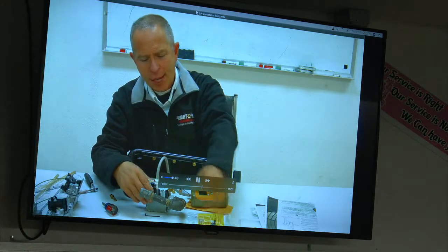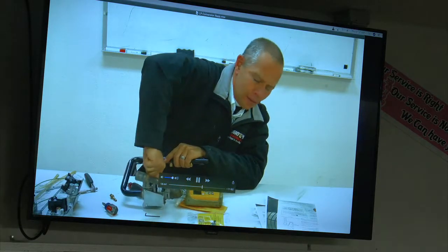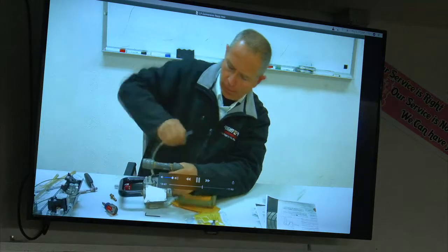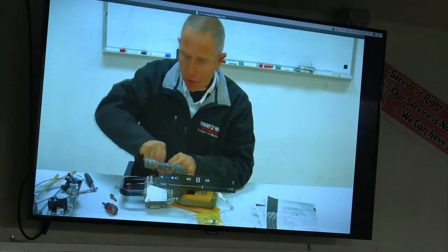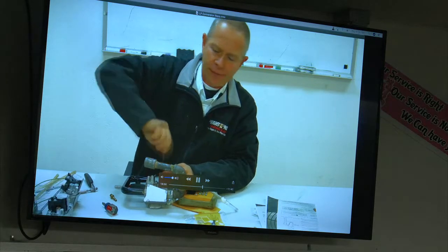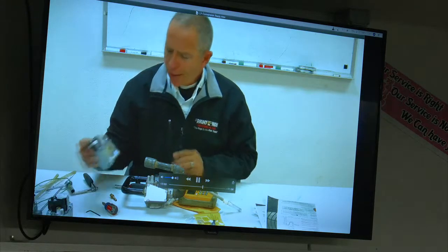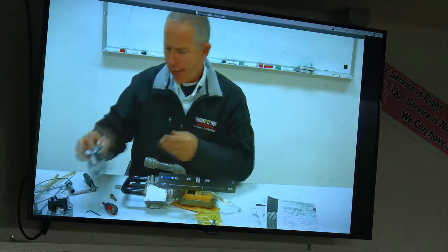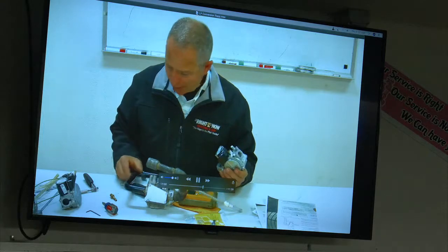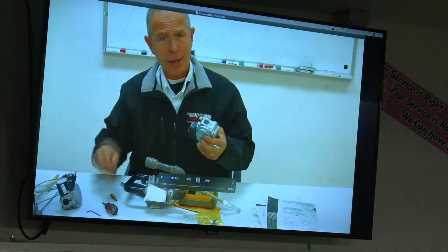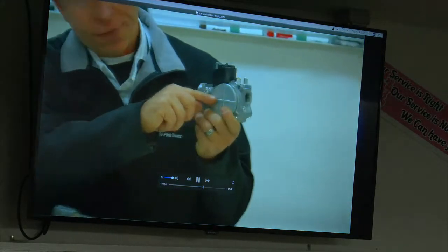So now that you have all that done, again, you're going to turn the gas off and disconnect your meter. And you're going to take that set screw and put it in and make sure it's snug. You're going to use a little bit of leak check and make sure you have no leaks on either one of those. The other style of valve that is most commonly used has the different barb. Same principle, different setup. So this one here, you're going to do the same program. It has an arrow on flow of which way the gas goes.